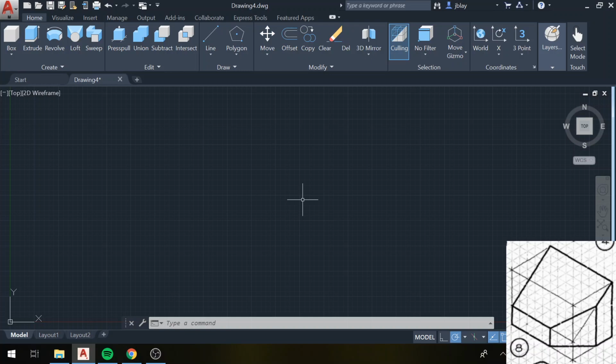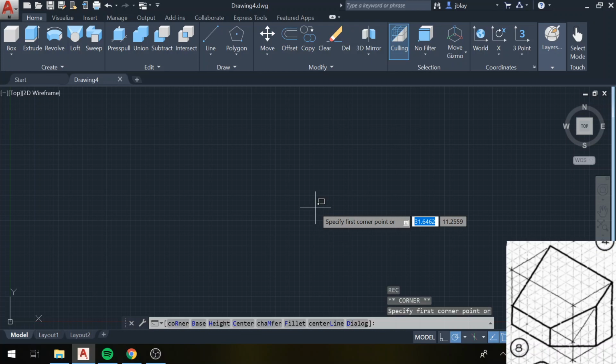there's really 3 sketches here that are being lofted, but it's not one loft because we don't have curve. It's 2 separate ones. I'm going to start with the smallest piece and then work my way up to the biggest. So I will start with the rectangle that we see up front, the one that is 2 units by 5 units. So 2 units is going to be ½ inch. So let me start a rectangle at the origin.